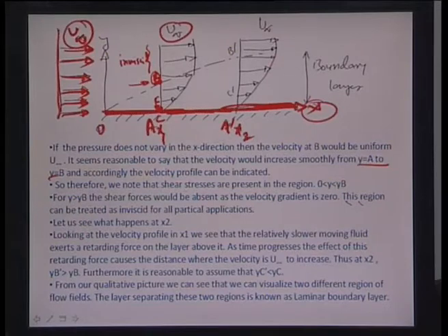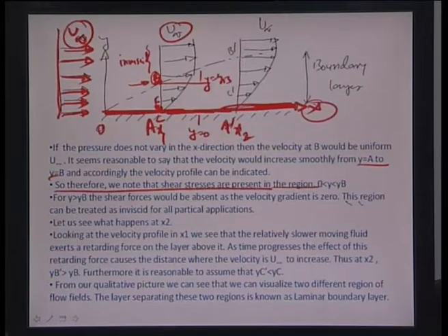So therefore we note that the shear stresses are present in the region 0 to yB, right, in this particular region. So y equal to 0 is this plane and y equal to yB is this plane, and essentially for any y greater than yB in this particular case, as you see, the shear forces are absent because the velocity is now all uniform and is matching very well with the initial velocity u infinity.